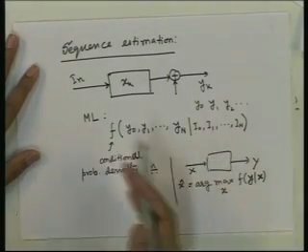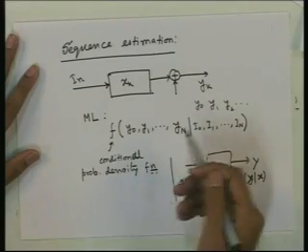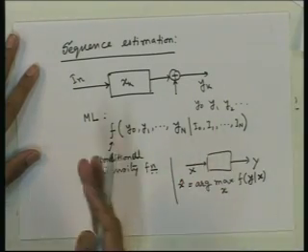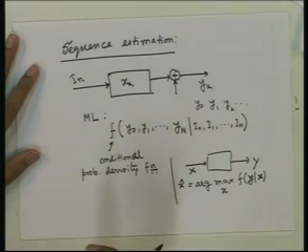Then after receiving 150, you will be able to decide about 50 symbols. So, there will be some fixed delay, but you will be able to estimate more and more symbols as you receive more and more. You do not have to wait to receive the whole block of symbols before you decide even the first symbol.